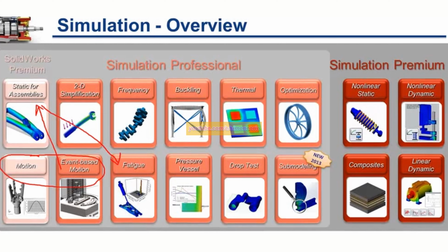From there, if we check out, the next phase might be what can we do for mass reduction. So then we're going to take that stress analysis and run some optimization where we use the integration between SOLIDWORKS and simulation to automatically change the design and rerun different scenarios. After we're done with the optimization, we're going to move on to a couple different methods of testing our part.